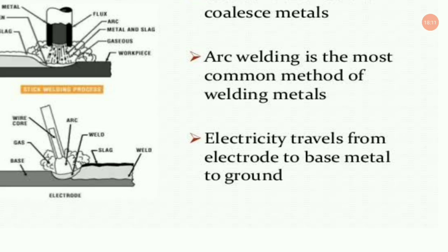Next we have another machine, which is known as constant voltage welding machines, which have a more flat characteristics curve. The slope of the curve is so small that any small change in voltage makes for an extremely large change in output current. These systems are generally preferred in automatic machines since they become self-correcting. For example, when the electrode becomes a bit closer to the arc, the arc voltage drops, raising the output current to a very high value. This current instantly melts the electrode and thus maintains the arc gap.